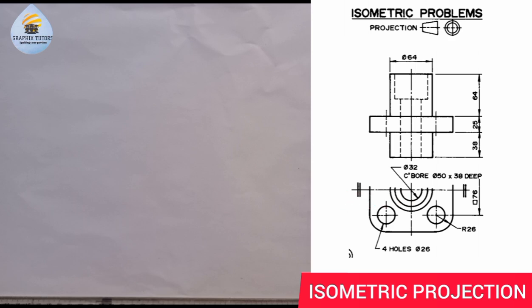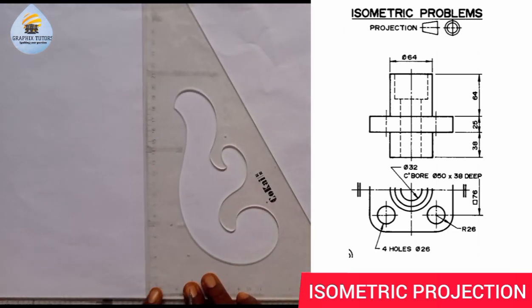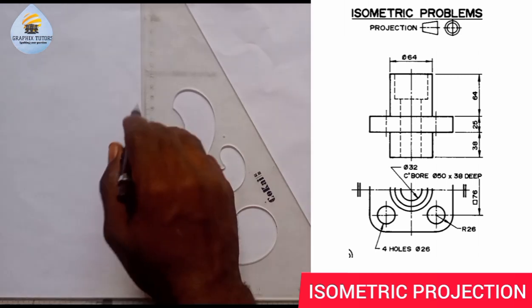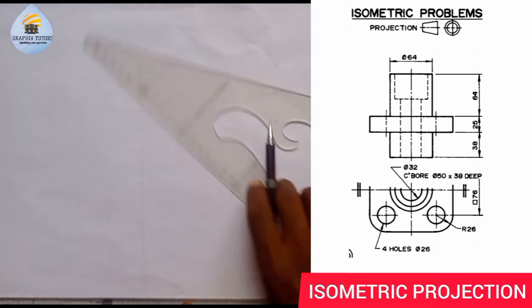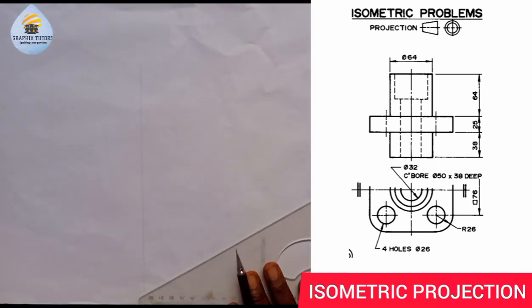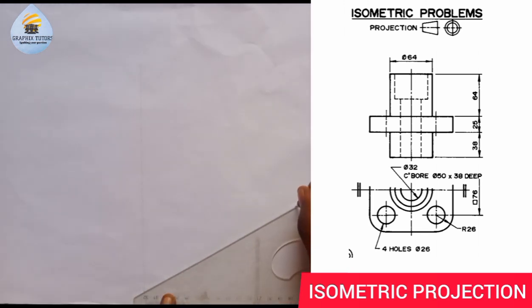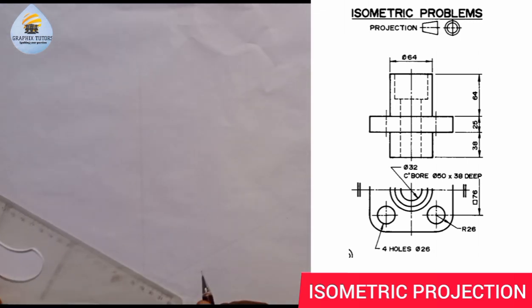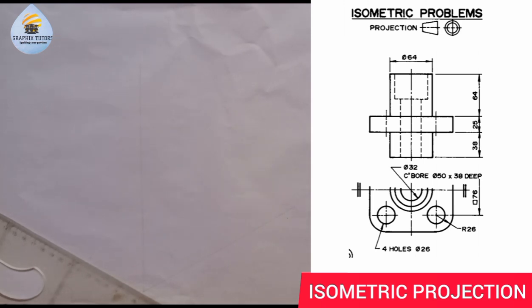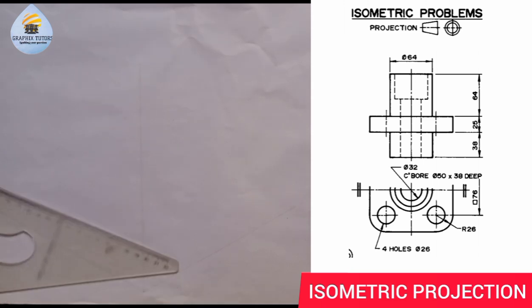So first of all, when you hear the word isometric projection, the first thing you should do is to draw your isometric axis. That is, you draw your vertical line this way, and draw your z-axis this way, and you draw the x-axis this way. Hope you can see that.